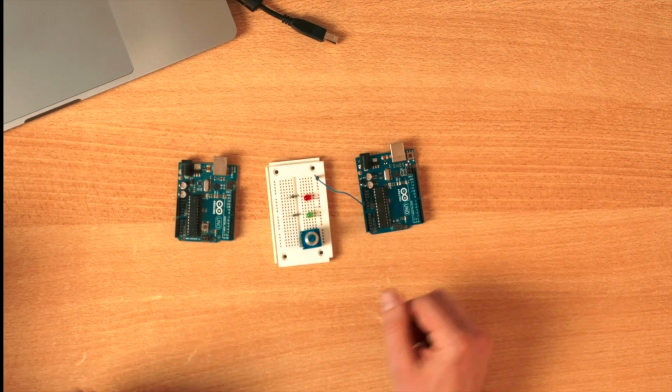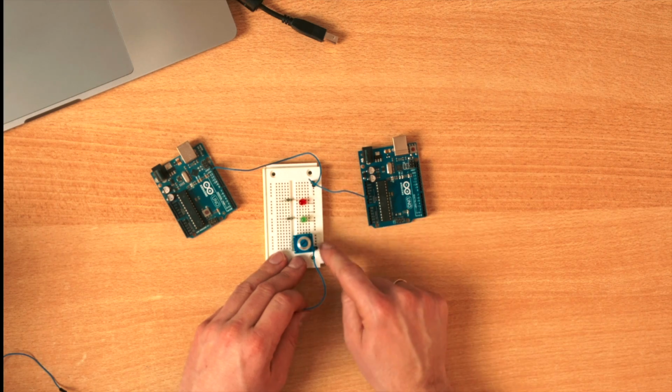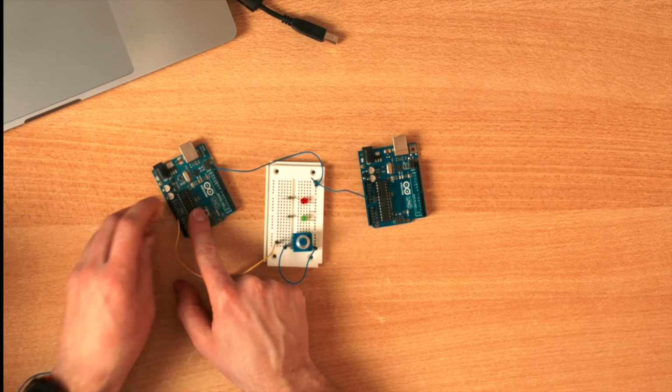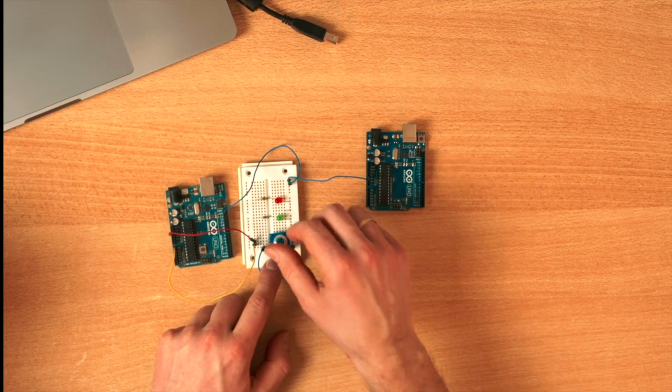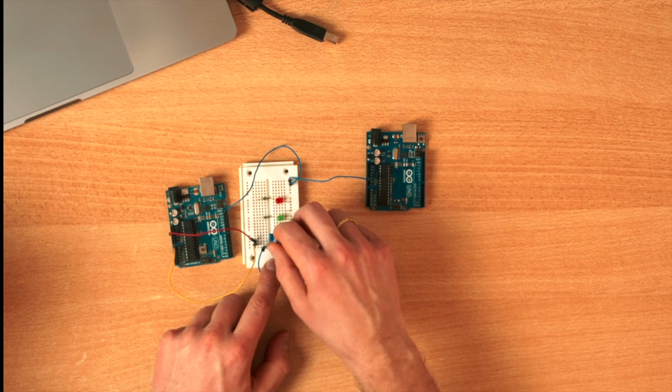I would like to conclude this video with an example where I use 2 Arduinos. This Arduino UNO R3 will be connected to a potentiometer, and this Arduino UNO R3 will be connected to an LED. So this Arduino sends this value to this Arduino, and this Arduino then sets the brightness of the LED accordingly. First, let's connect all of the ground connections. Go around. All of these contacts here are connected to ground. The wiper to output the signal to A0, and I also need 5 volt. So like this, I should be able to measure analog voltage.